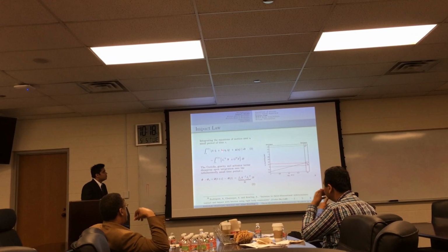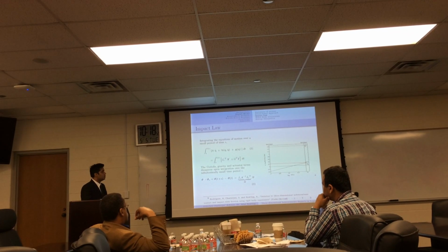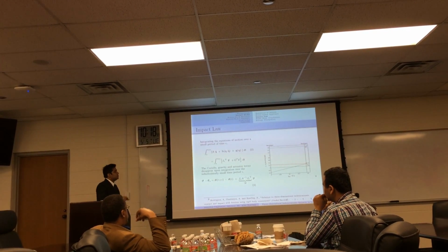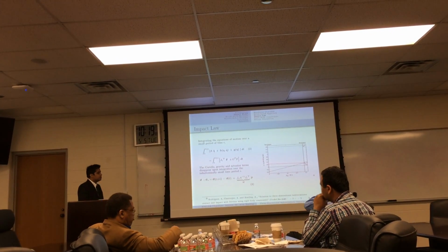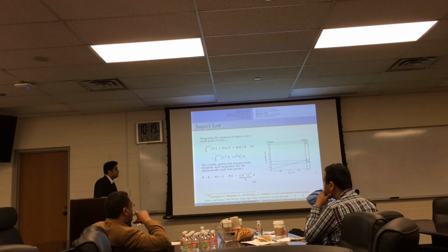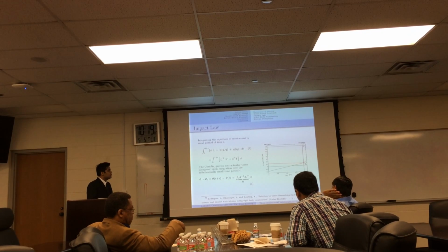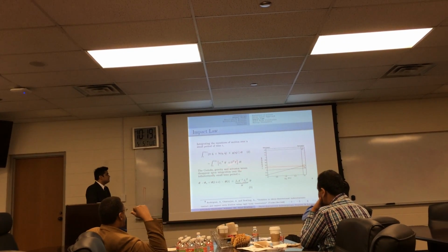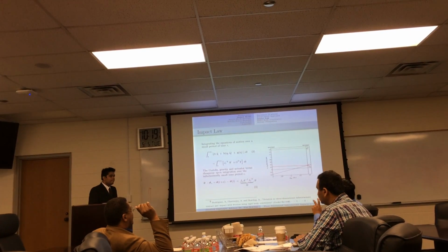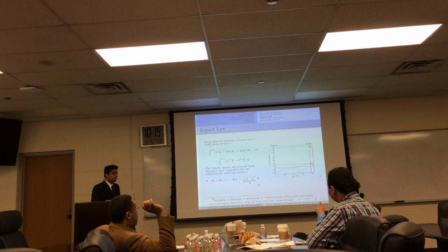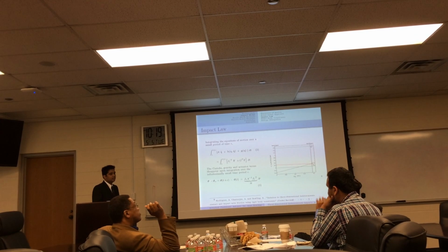So essentially, the Coriolis terms and the gravity related terms, which are just functions of q and q dot, are going to be bounded. And when we integrate them over a very small period of time, they are going to be negligible. The same goes for the torques, because the torques are going to be bounded. We can neglect that. However, V here is J_C times q dot, right? Yeah. Okay.